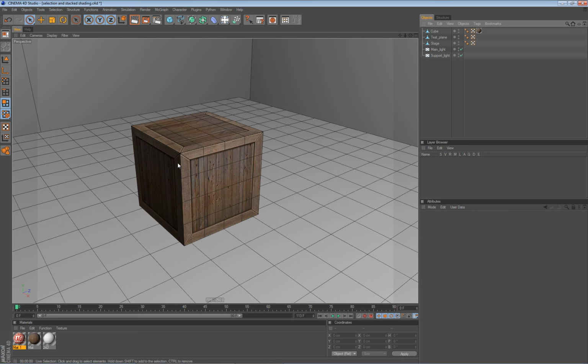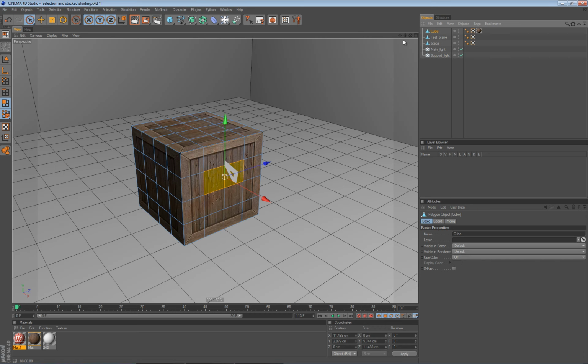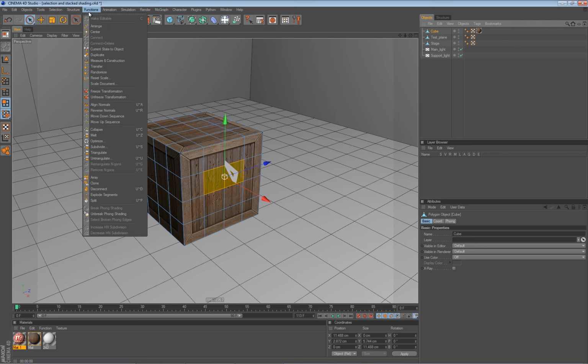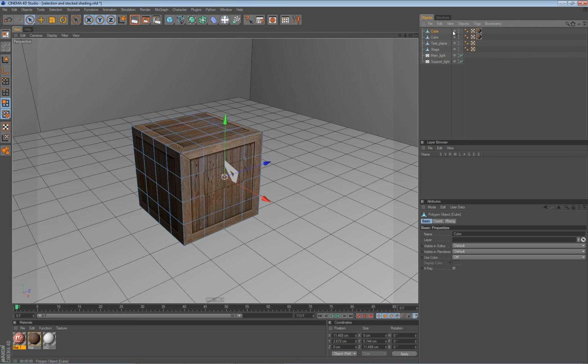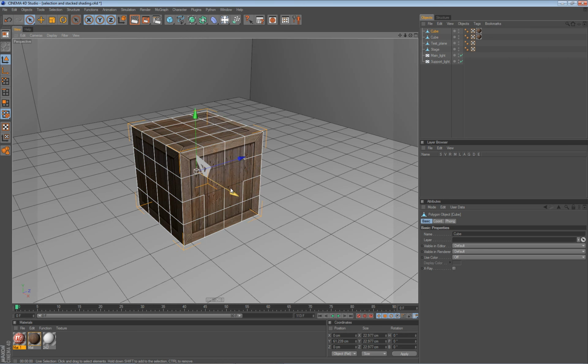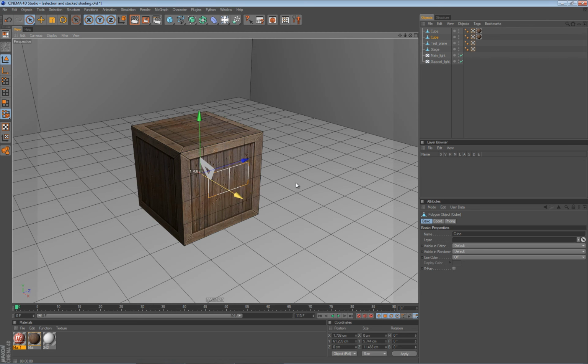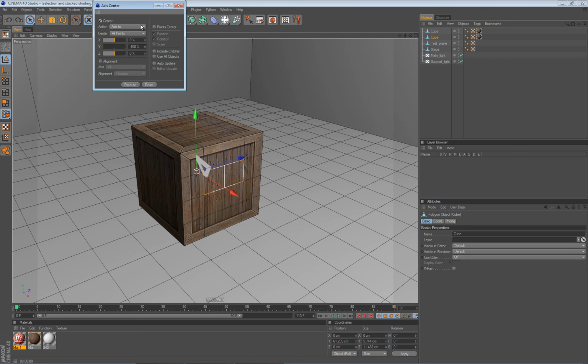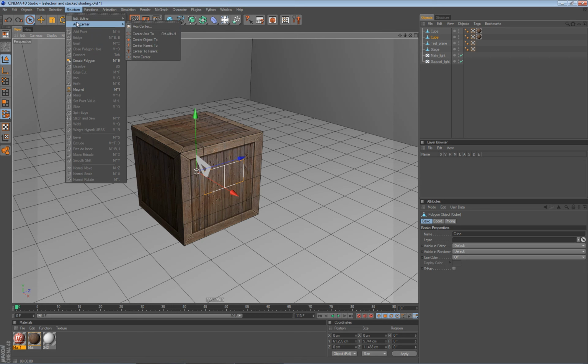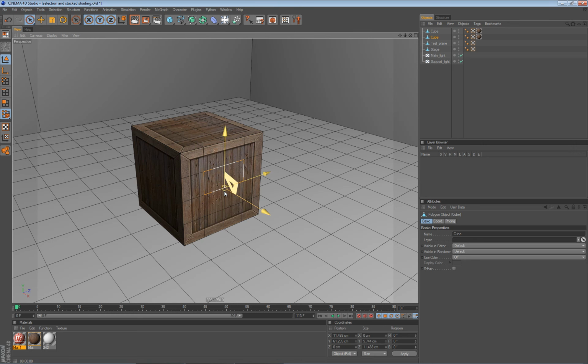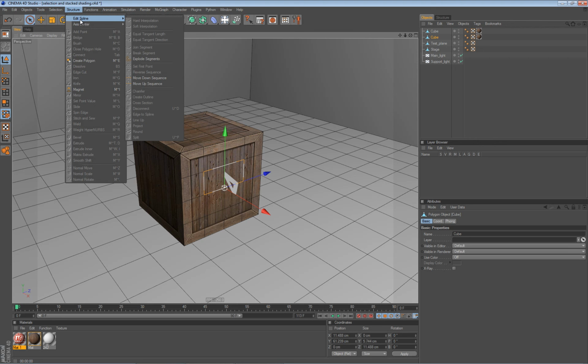The second way would be to split this. This is a command to create new geometry, so let's just do that. Let's go Functions, Split, and we will get a duplicate of our selected faces. You can see that. I just want to center the axis. I really like things to be neat. Here I have a shortcut assigned, Center Axis To. This is Control Alt plus H, and if I press that, it will put the axis exactly like here.